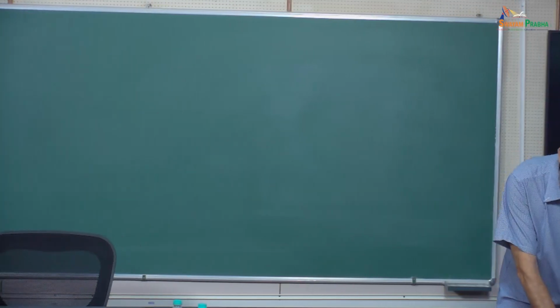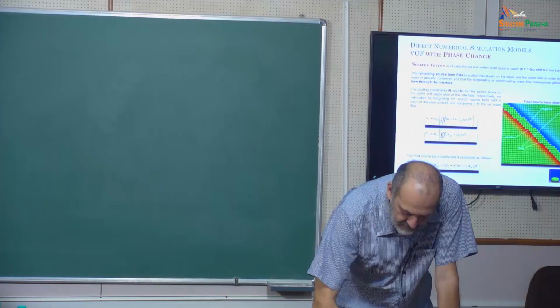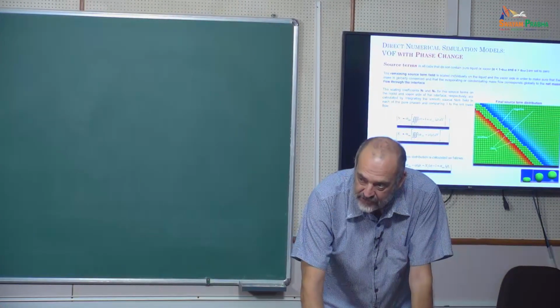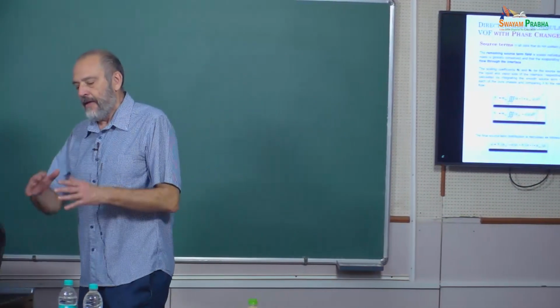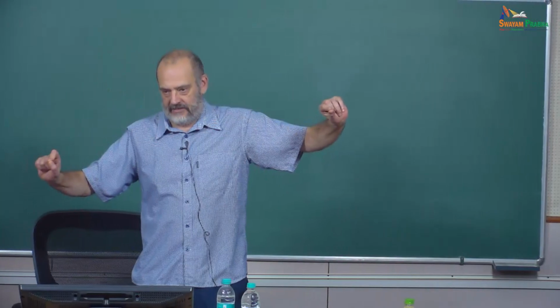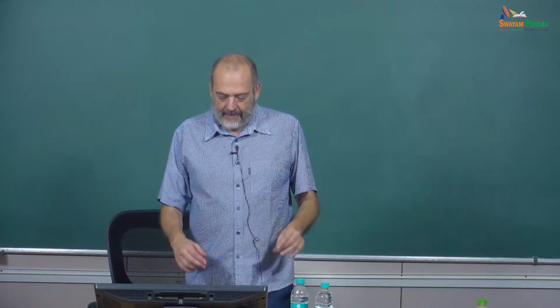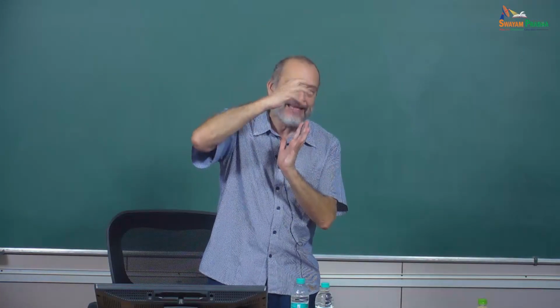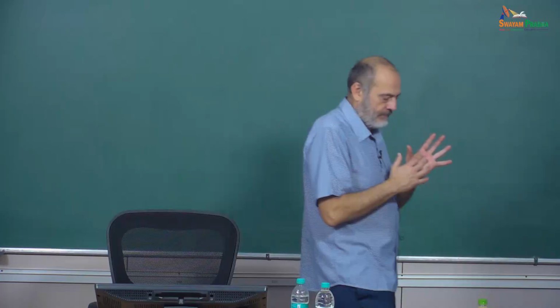So there is a gradient of alpha, okay? And we have a flow rate due to the phase change, because the evaporation is going from the liquid to the gas. So in this case, we are going to have at the end two interfaces. And the position of the real interface is something between the two, okay? We don't know exactly which is the position.